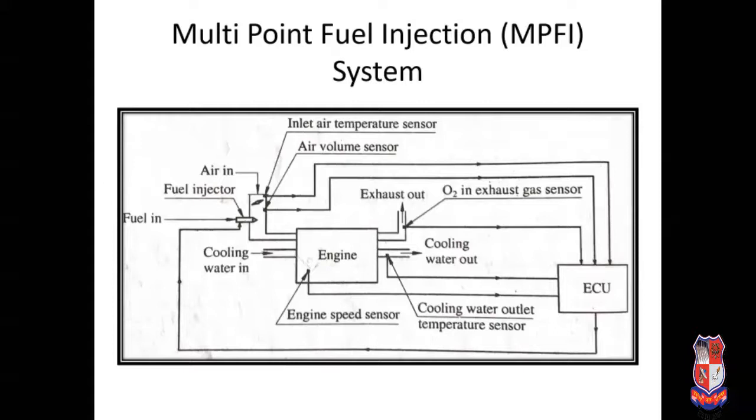The basic requirement of the MPFI system is that there are individual injectors, or we can say one injector is required for one cylinder, right? So per cylinder one injector is used. In some cases, the number of injectors used for one cylinder may be 2 to 4, according to the requirement of the engine.